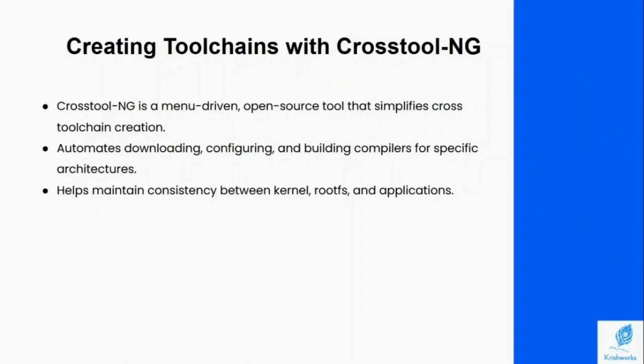Creating toolchains with crosstool-NG. Crosstool-NG is your best friend for creating cross toolchains. It's open source, menu-driven, and automates the complex tasks of fetching, configuring, and building compilers for your specific architecture. It ensures consistency across your entire embedded Linux environment.